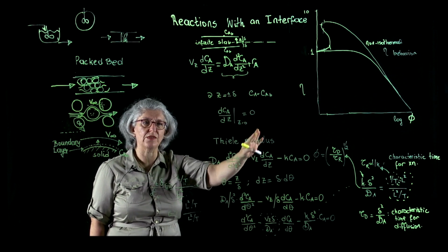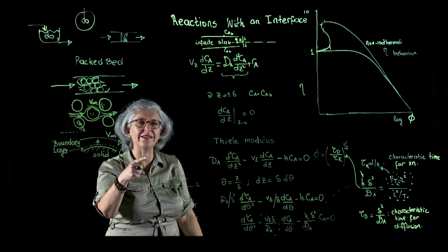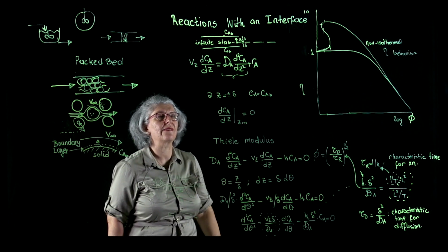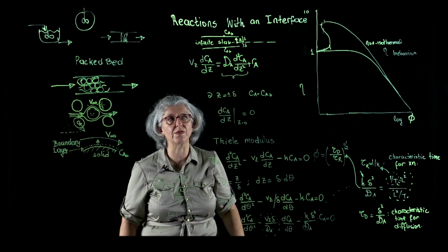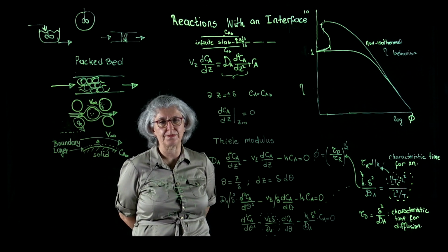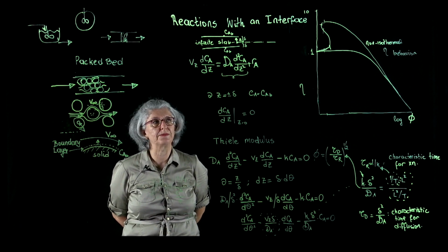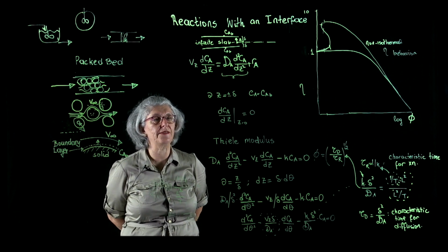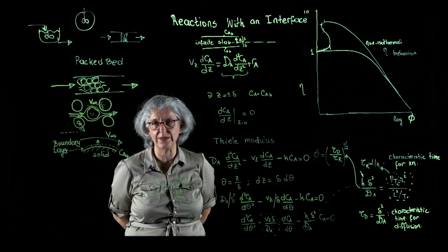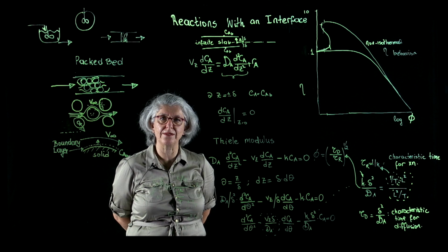In other words, our reaction rates could be 1,000 times faster, that our temperatures may increase 1,000 times faster than the isothermal situation, and that might lead to disruptions in the catalyst or in the reactor. This is something that we have to evaluate, not by only solving the species conservation equation, but also we have to solve energy balance along with it.